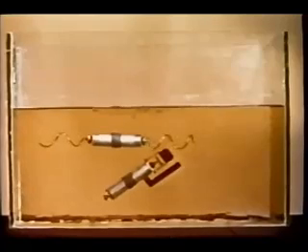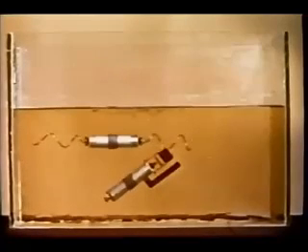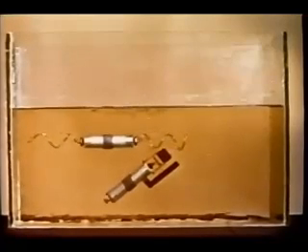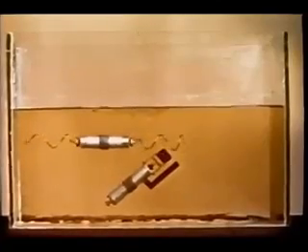The last example I will show of low Reynolds number flow is that between two parallel plates separated by a very small gap. This arrangement, known as the Hele-Shaw cell, has a special interest because, paradoxically, it offers a means for making visible the streamlines in certain cases of ideal flow of a non-viscous fluid.